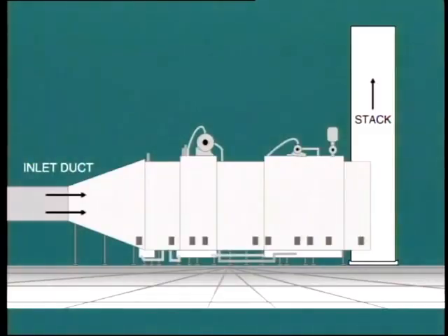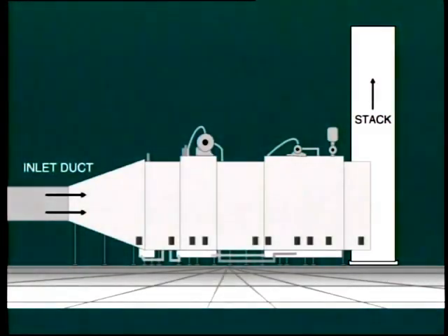Another feature of the lower gas temperature is that it effectively reduces the superheat steam temperature that can be achieved from the HRSG. Most HRSGs operate with a final steam temperature of 850 to 950 degrees Fahrenheit. In order to make use of this gas at the lower temperature end, it is quite common to construct an HRSG which incorporates several independent pressure levels.